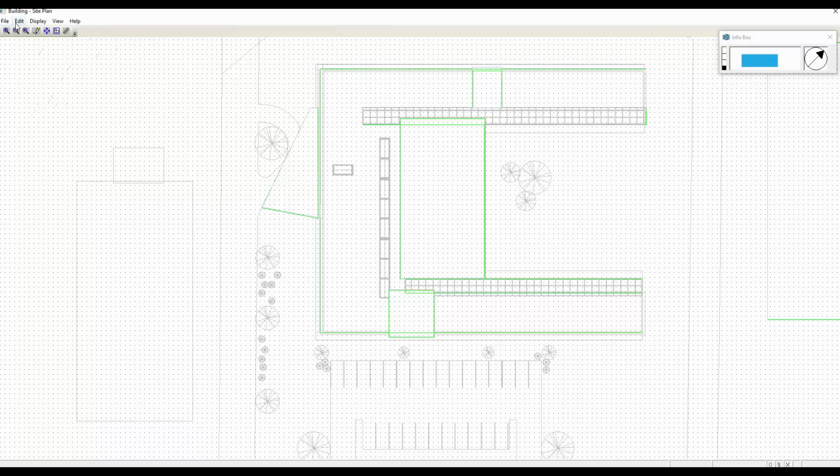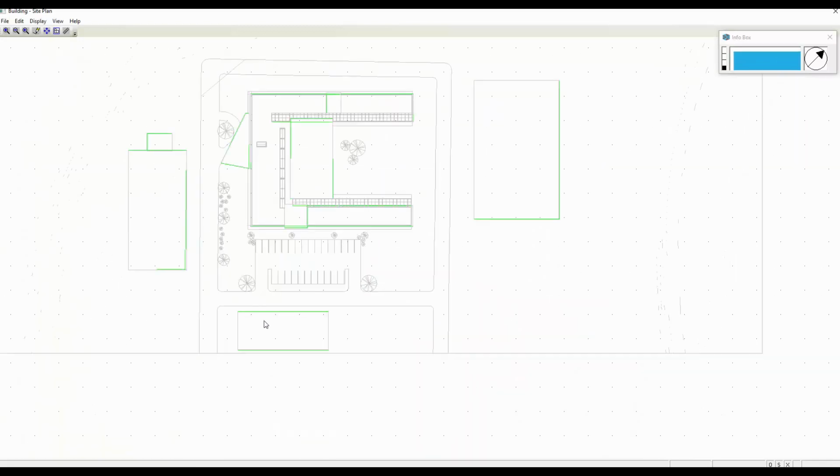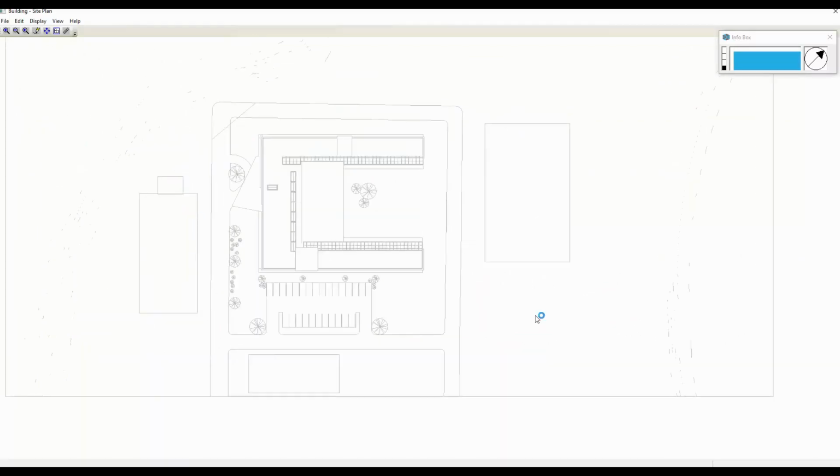We then have our other building. Let's say, for argument's sake, the main body of the building is 25 meters high. We have a service tower 30 meters high. Edit, Graphically, I'll do the basic building first. They're all going to be the same. Click around the boundary of the space, the building being shown. And of course I could switch my orthogonal back on. Then I do the service tower, Edit Graphically. I'm going to make that 30 meters. Clicking around the shape. And I can describe. Then we can see these other two buildings.